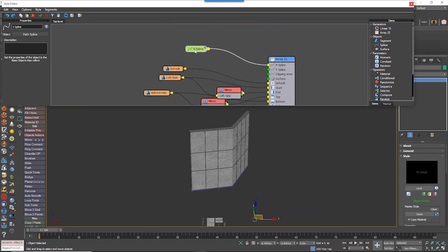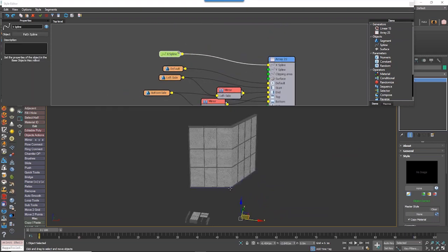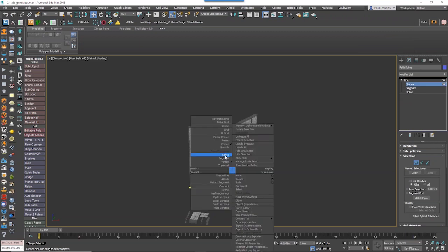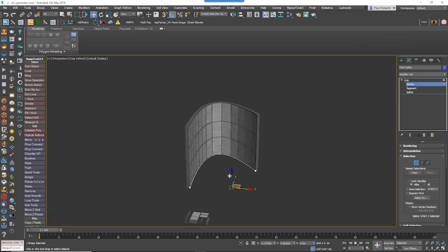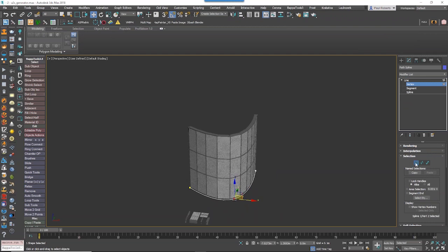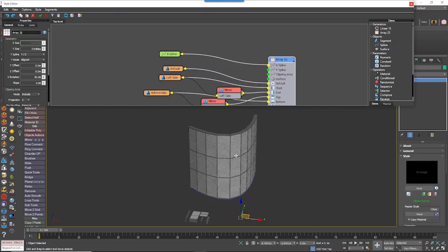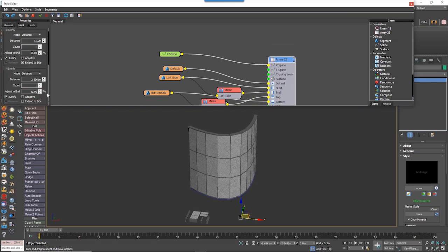So far I've defined the x-axis of this spline using a spline, and this would allow me to curve this as well. So if I hit smooth here, for example, I can very easily create a curved curtain wall, which still has control for the spacing between these divisions from down here and here, all very nifty.